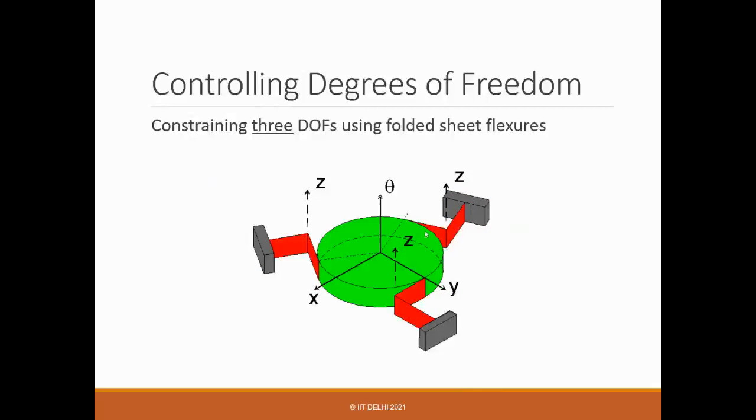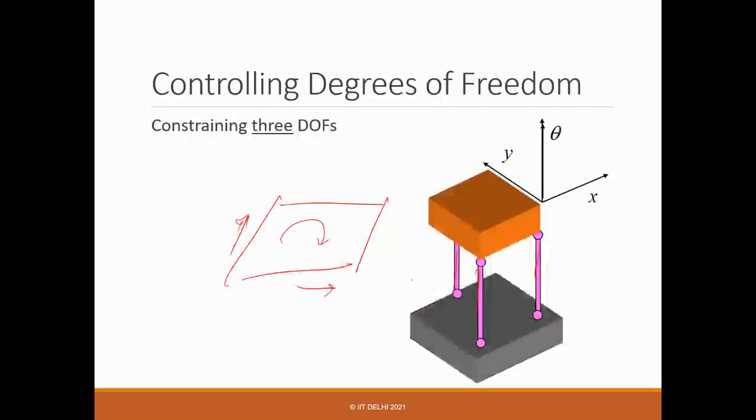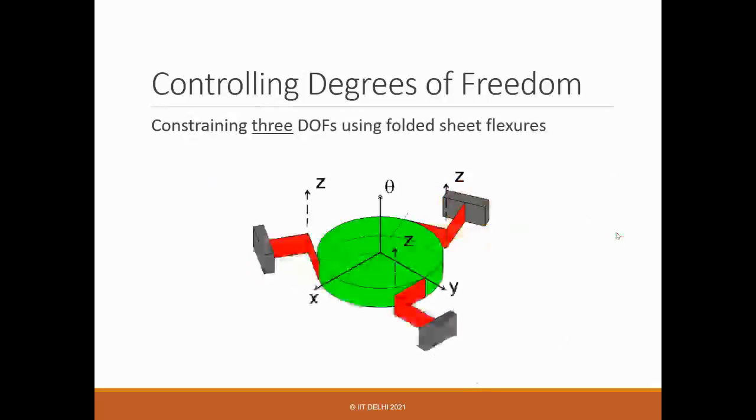And in this case, no matter where you move, you don't have any shortening effect. In the previous case, if it moves along x, y, there will be some shortening effect, right? Many times we call it parasitic movement, but in this case you don't have it. And one way to look at it is I have one design made here.